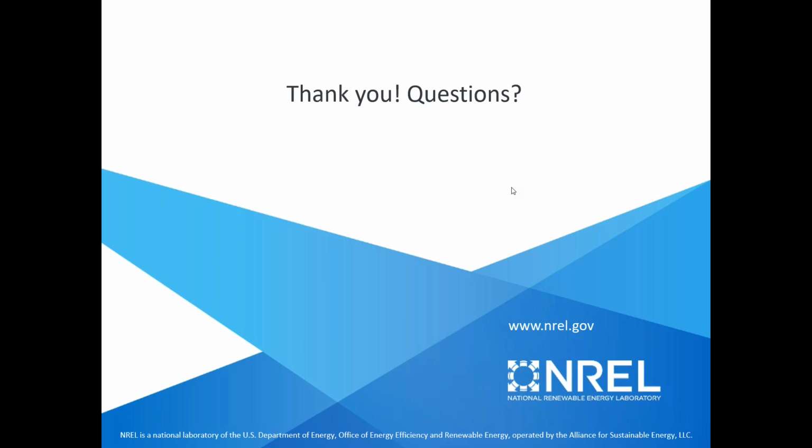But there would be some options, depending on the system configuration, to be able to, in a hacky way, represent DC optimizers using this multiple MPPT feature. If you are interested in presenting us with a system configuration and working through how to hack SAM to model it with us, I would encourage you to either post on the support forum of the SAM website or to send an email to our sam.support@nrel.gov email, and we can work with you and then maybe post that as an example of one way to hack this new feature to better represent DC optimizers.